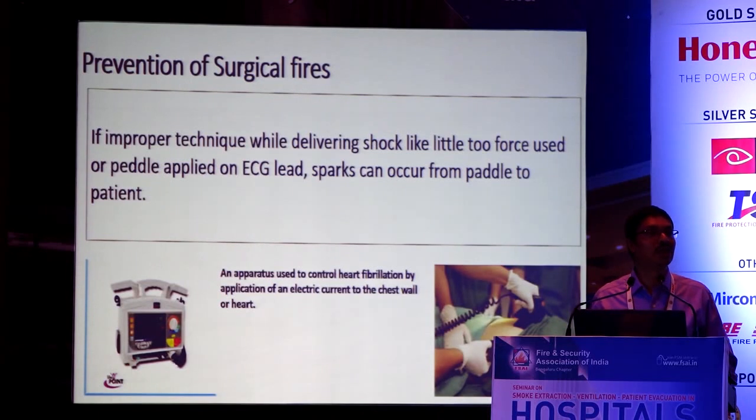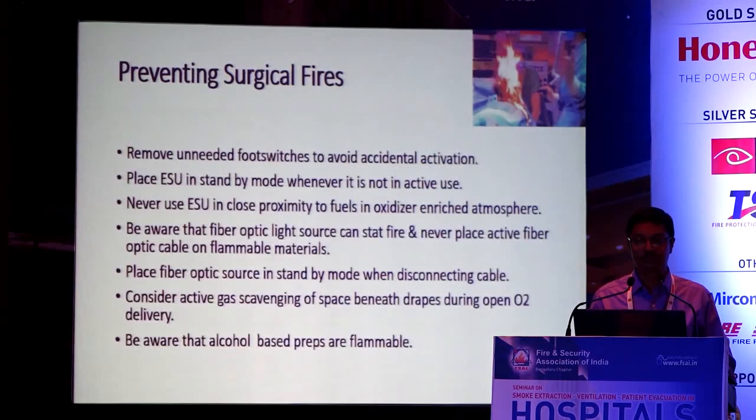So how to prevent? Remove the unneeded foot switches to avoid accidental activation. Use the electrosurgical unit in standby mode whenever you are not using it, because when you are firing, there is RF current flowing at the tip. Never use the ESU in close proximity of fuel in an oxidizer enriched environment, which I was talking about. The fiber optic light source I was talking about.